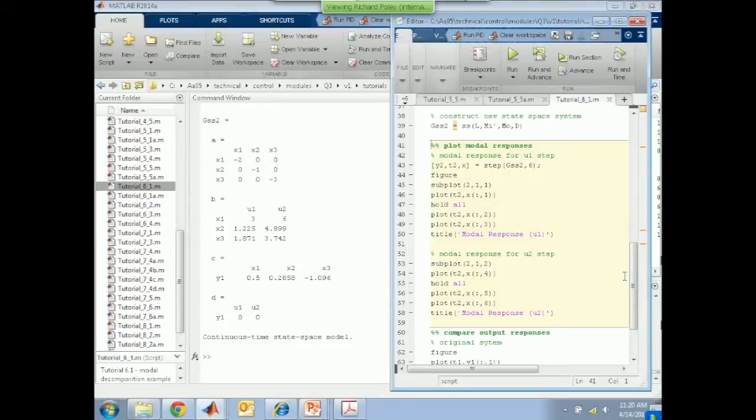And now here's the thing. For this particular choice of states, because we've got a fully diagonalized spectral matrix, we must have fully decoupled internal states now. Each state is only dependent on its own state. So we've got qi dot of t equals lambda i times qi. So they're fully decoupled. It's a first-order differential equation. There's nothing else in there.